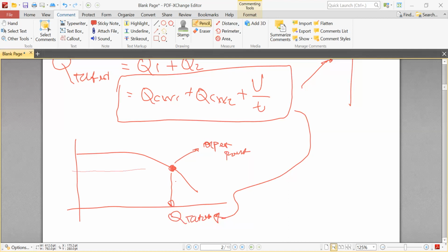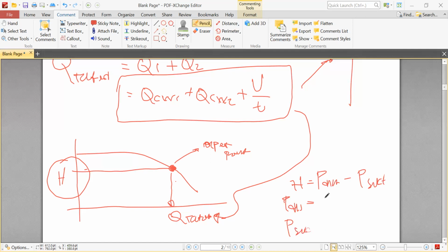As in my previous video, the head is just the difference between the discharge pressure of the pump and the suction pressure of the pump. We have to first calculate the discharge pressure of the pump, and also find the value of the suction pressure of the pump.